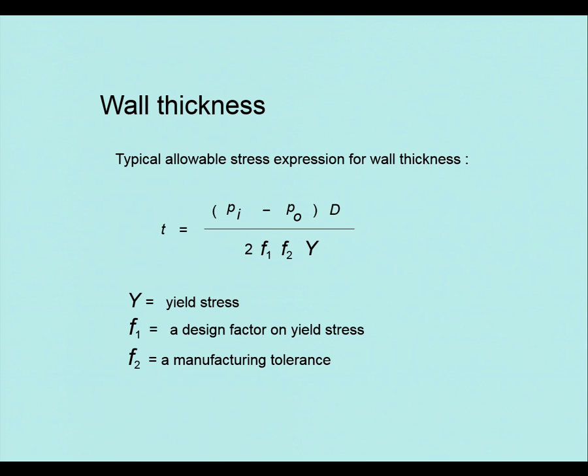Now, if this is really thick wall pipe, the stress strain curve of those is more appropriate to that. If the pipe is thin wall made out of plate, then this changes. And you get a series of them. And these are what are called modified stress strain curves. So that your shoulders disappeared.